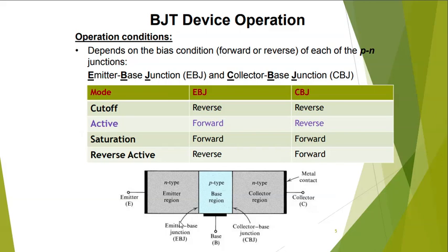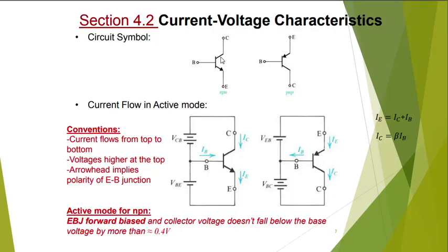But because I had promised you that I'm going to cut to the chase, forget about it. I'm going to tell you exactly how it works. These are the 2 types of transistor that I told you about. This one is NPN, this one is PNP. You remember what the hint was to remember NPN? The arrow is down. In PNP, the arrow is up. And the emitter is with the arrow. So when the arrow is down, collector is up, emitter is down. When the arrow is up, emitter is up, collector is down. Base is always here in the middle.